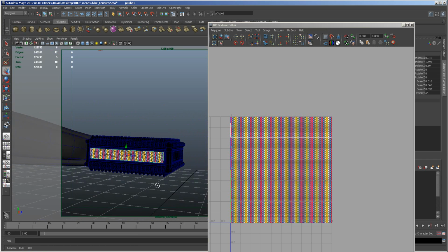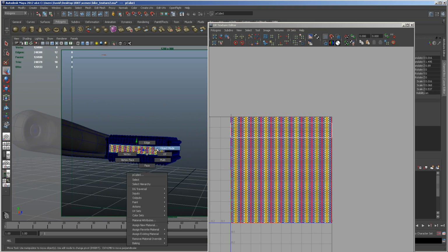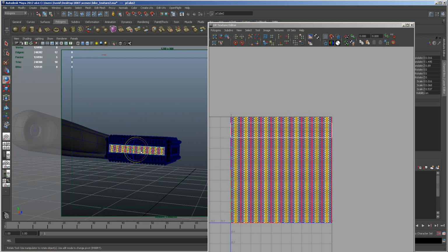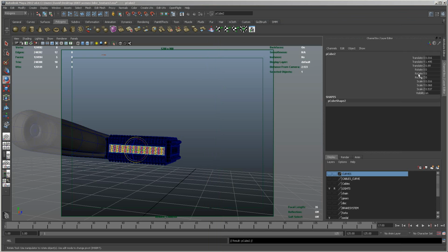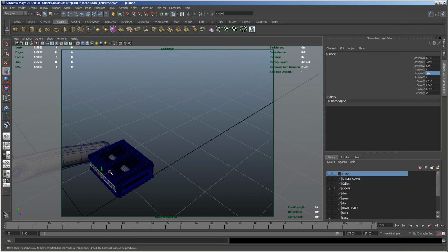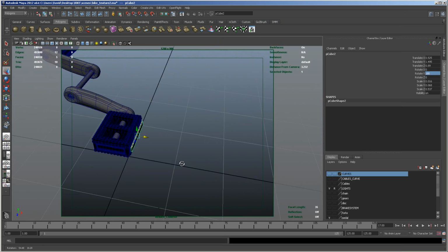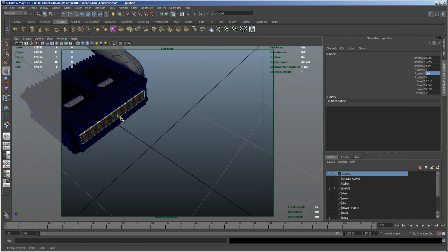And now the reason that I didn't do the other plates is because I'm going to use this as a base. So I'm going to press Ctrl D to duplicate. I'm now going to press E, and I'm going to rotate it around the Y-axis like this. As you can see, the Y-axis going up, but I'm going to translate it 180 degrees. Now I'm going to press the W key and I'm going to move it through and into position on the other side, like that.